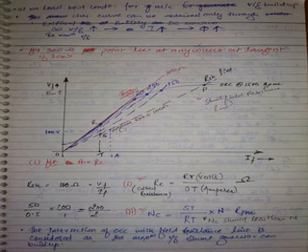Same field current, if the speed increases to 2000, for example, then N1 is 1500, N2 is 2000. E1 is 10. What is E2? Is the point clear? So calculate like that.